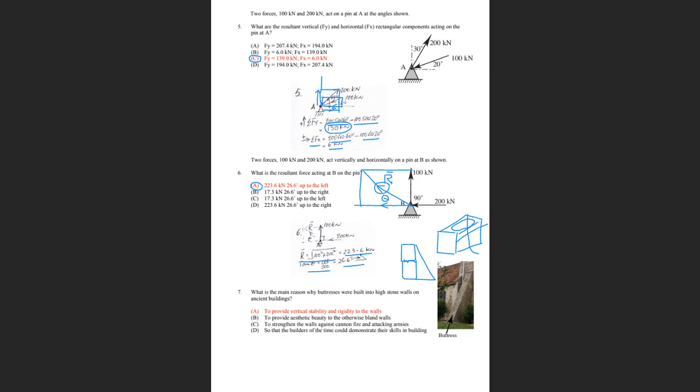Then they fill the holes with concrete, and at the bottom you've got special blocks which have a cutout in, and then when they're forcing the concrete down, you see the concrete coming out here, and you know that the wall is totally compacted with concrete.